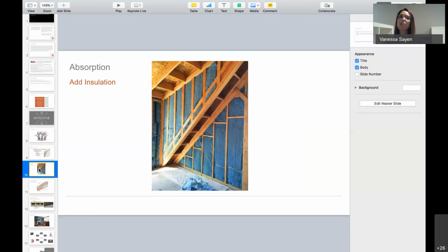One thing that we like to remind everybody is that it's important that we use this insulation to match the depth of the wall cavity. We've seen on a lot of jobs that people just stuff the insulation tightly into the cavity and they compress it. And by compressing that insulation, it defeats the whole purpose of absorbing the sound qualities. So we want to make sure that the depth of that insulation matches the wall cavity. Let's just not push it all the way in. And again, this technique or this tool is effective for the middle and high frequencies as well.